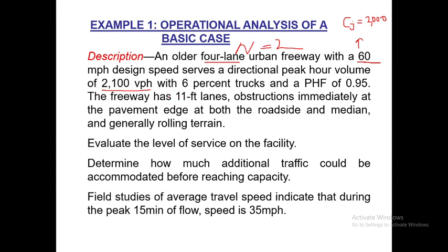We need the 15 minutes peak volume. We don't need the hourly one like that. So we have to convert this one to SF. Okay, with 6% trucks, what is the 6? The 6 here is the percentage of trucks. So PT is 6%. And PHF is 95%. I told you PHF is always given data.